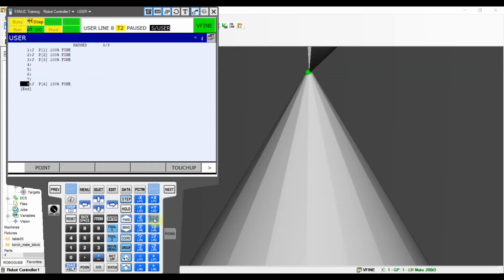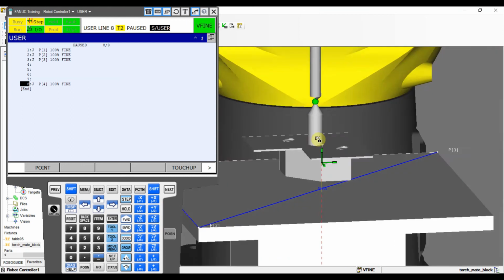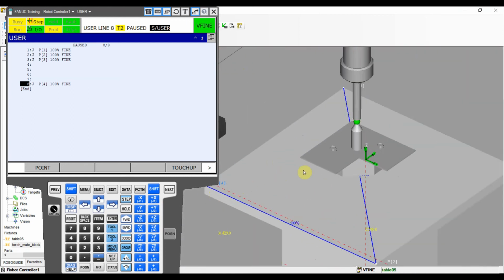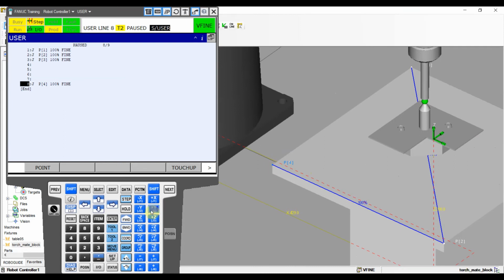Let's go a little bit higher. Up. Perfect. So we add the dots. And what's going to happen now, guys? Now our 0, 0, 0, take a look at that. Position, our user frame. Look, so we are 122 millimeters from here in X, 123 in Y, and 75 millimeters in Z, right? So you need to calculate like this, this, and up.